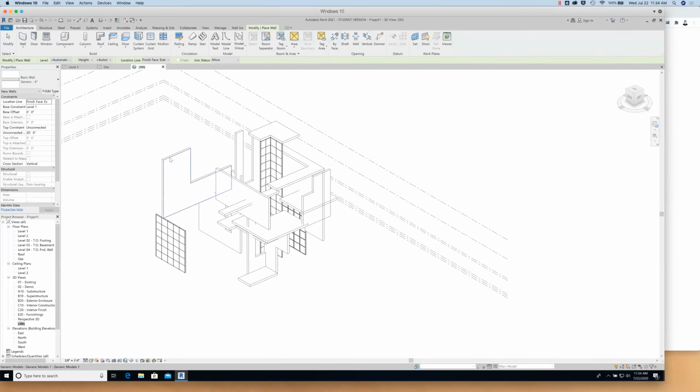So what we're going to do is start selecting the vertical faces of this extrusion that we brought in from Rhino, right? And so each of these walls is going to be 6 inches. And so it just basically wraps around itself. And what I'm going to do is basically start to put reveals on the sides, side edges, the front edges, the back edges, okay? So I'll do it for that one. I went around and got all the vertical faces for that.